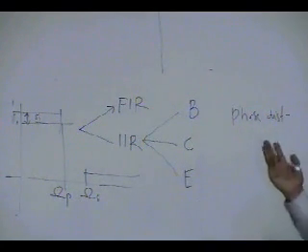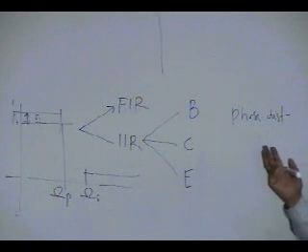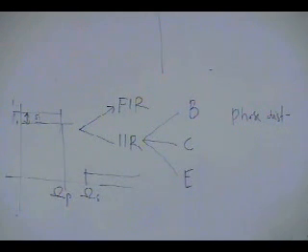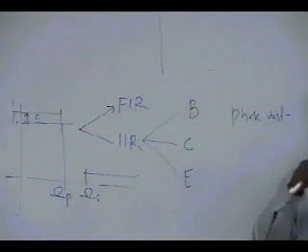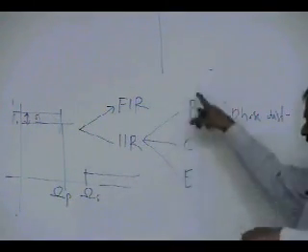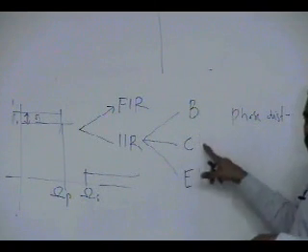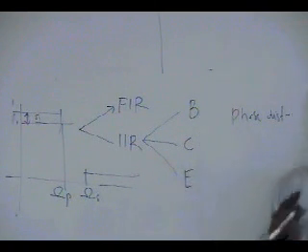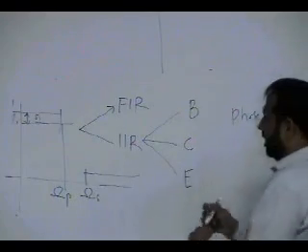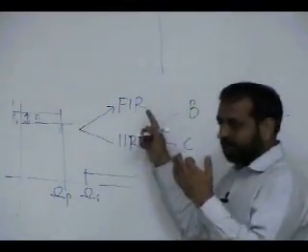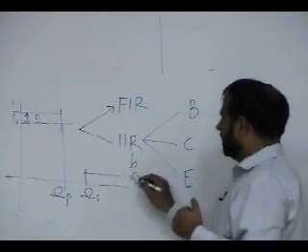It's more challenging in the part where you really don't know the specs. There are no specs, so you have to design things on the fly. Whether you are doing IIR, you cannot first find the specs in real time and then say I want to do this or this or this. No, you have to design a filter. In the second part of the course, dynamically you get a buffer of data, and you have to design an IIR filter or an FIR filter with B's and A's in it.